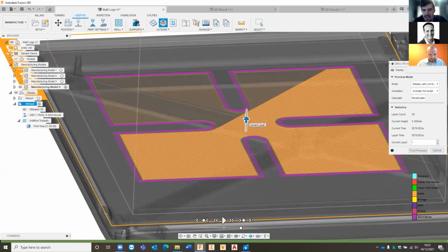You can see it has quite a big jump initially, and that will be because of the number of layers that we're allowing it to show at once. As soon as we zoom in, it'll increase with smaller increments, and we can jump fewer and fewer layers at a time as well. We could also look at specific layers, or we could bring our timeline right down at the bottom all the way to the beginning, and then play through this, and it'll run through the entire simulation step by step, and you can see how it will run through the printing of this particular part.